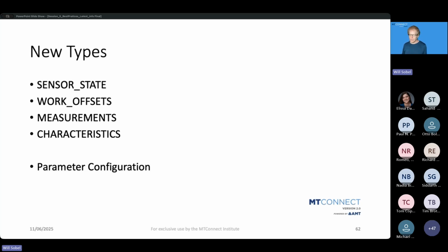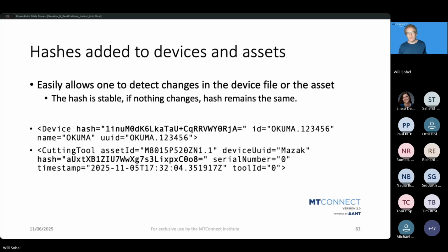for your thermocouple, what your PID parameters were, if you know what that is, basically how the temperature approaches a certain value, and how you configure it to approach that and slow down as it's starting to get to that temperature. So you get the exact temperature and maintain that exact temperature. So things along that line, configurations for flow rates and all that kind of stuff. We wanted to be able to represent those in the description of the machine.